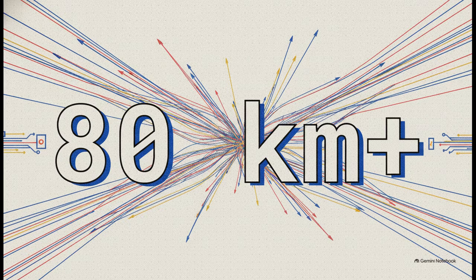What does that mean for us? It means there is absolutely zero modal dispersion. And because SMF eliminates that chaotic bouncing, it can achieve practically infinite deterministic bandwidth over staggering distances. We're talking 10, 40, even 80 kilometers or more, literally limited only by the electronics sitting on either end.